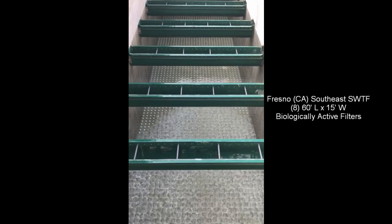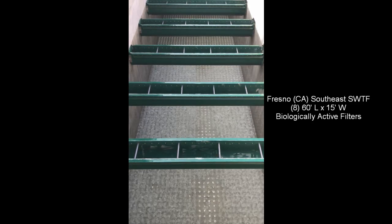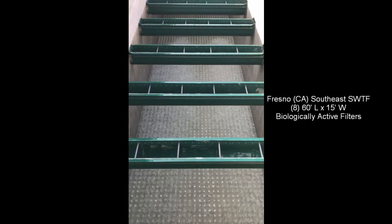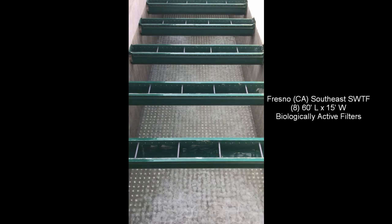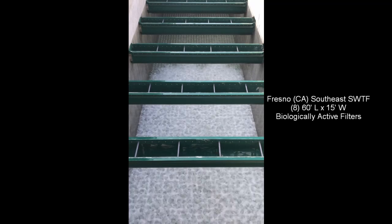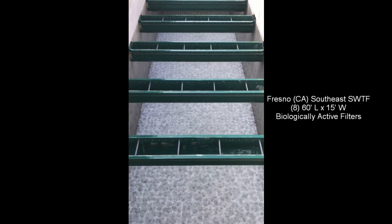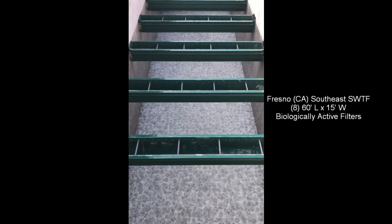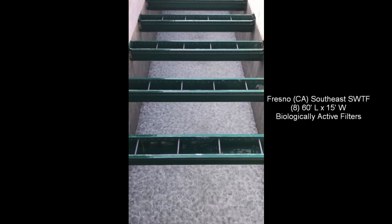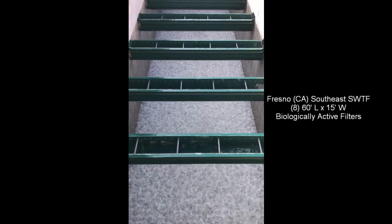The underdrain flow distribution test provides a straightforward visual test for proper backwash distribution. At first, the air scour only pattern is observed, which often reveals the deficiencies of poor distribution underdrains and if the underdrain was installed incorrectly. During this test, the water surface must present a very uniform turbulent appearance without dead zones or boils.